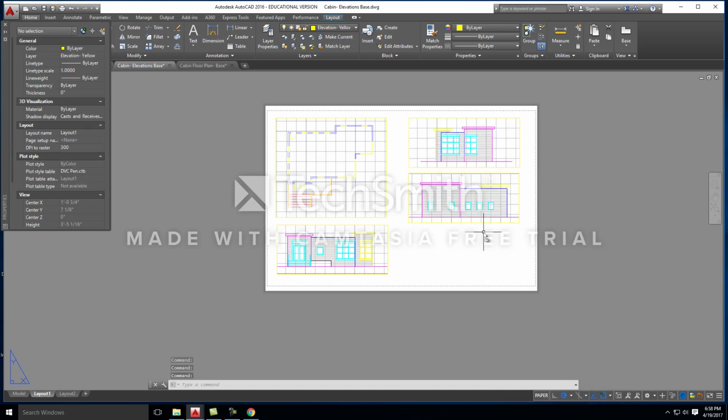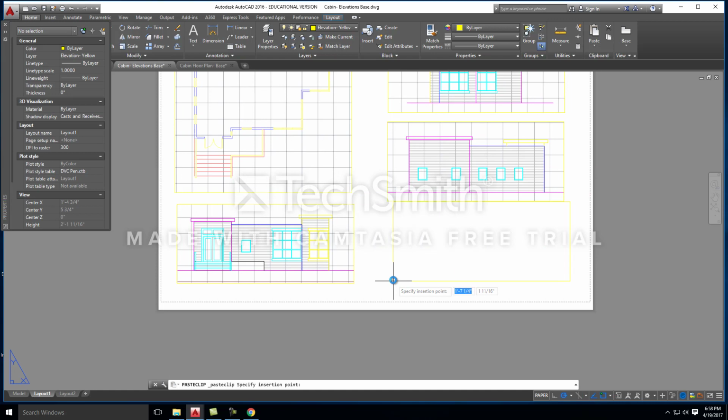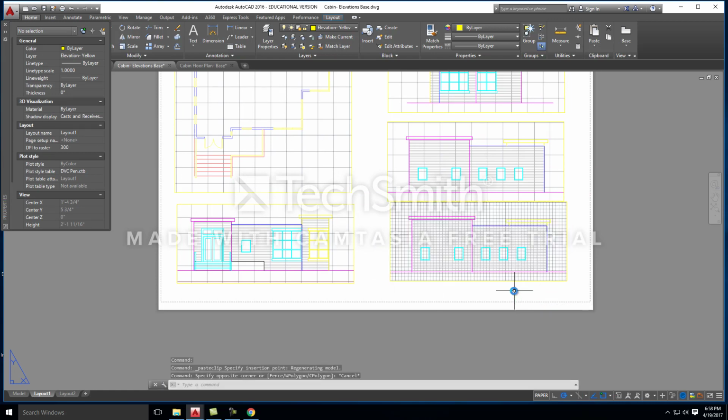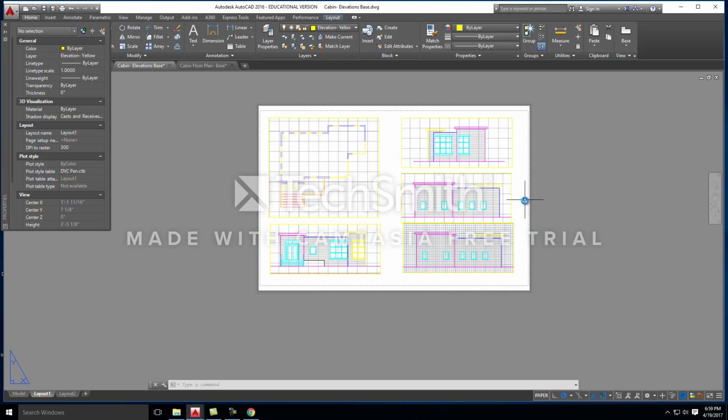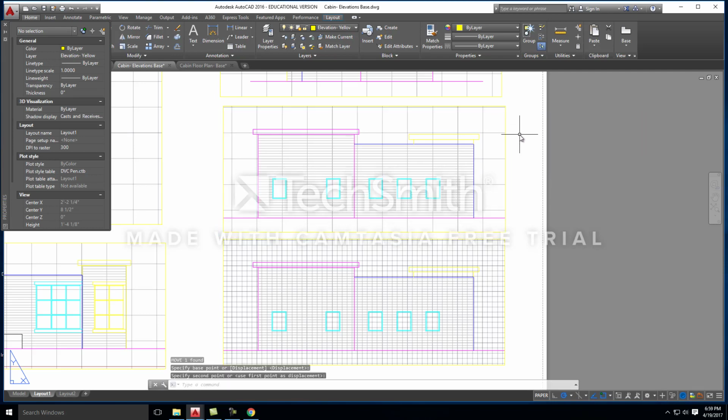Like so. And you know what I'll do, I'll just copy this one another time. We'll pretend that's my 4th view. All right, and another thing that you might do is line up, or make sure that you have a common alignment with some of your other roof parapets, okay? So you might want to align right here, this blue line, that's the same parapet as this blue line. So you might want to align those 2 lines as well, and also your floor elevation, or your common floor elevation. All right, so those are just a couple things to think about prior to plotting your sheets in Paperspace.